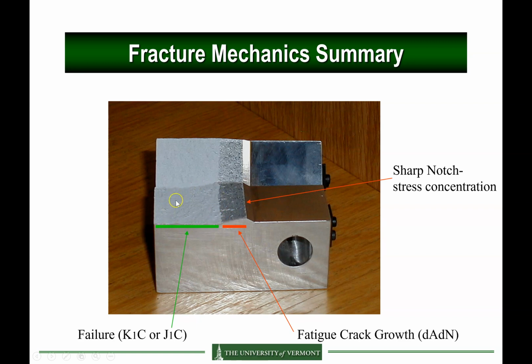and it's from this test that we are measuring the fracture toughness. So if you know that your material is brittle, then the K1C analysis is what's used as a method. And if you know that your material is going to be very ductile, so if the test is performed at high temperature, for instance, then J1C analysis will be more appropriate. Okay, so in this test, lab number 6, we are using only the K1C analysis.